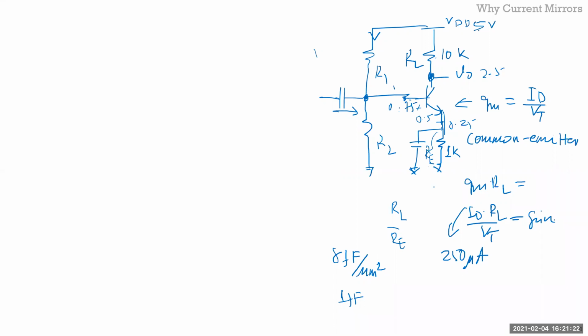So in IC design, that's why you're usually given a power budget. And because of that power budget, each of the circuits, you'll be given how much current you're going to draw. And you basically just bias those circuits by those currents, okay? Now, this is where current mirror comes into picture, because in order to create a current source, typically a current source is created through a band gap reference, okay?